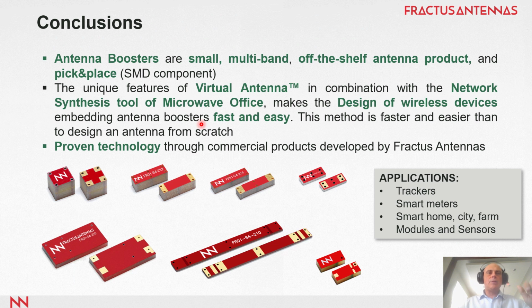So to conclude the presentation, we see that the antenna boosters are small, they can be multiband, they are off the shelf, so ready to use. From the very first day we are designing an IoT device, we have the product ready to use, and they are pick and place, they are SMD components, which is very convenient for mass production because the quality of this assembly process is very, very controlled through the pick and place machines.